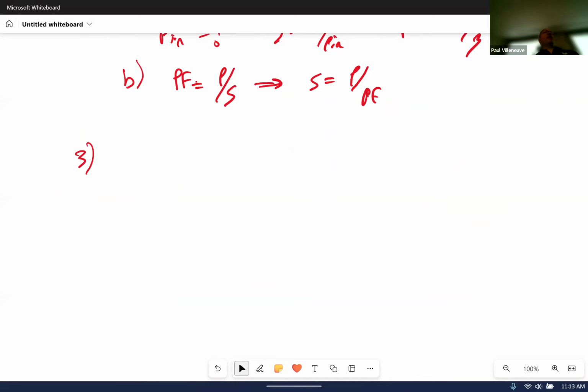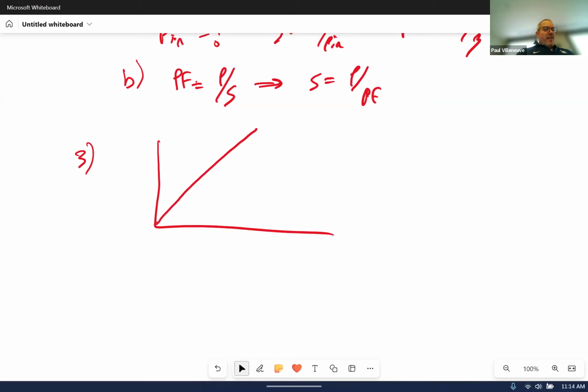Well, I gave you tabular data, correct? So if you're not comfortable working with tables, draw a picture. So we have the air gap line. We know it starts at 0. And then at 480 divided by the square root of 3, right? Because we're going to do things in single phase quantity.